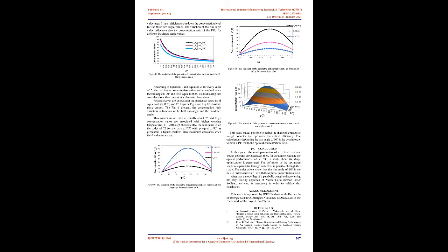Thermal losses from the receiver pipe to the ambient. The net thermal output can be theoretically calculated from the energy balance shown in Fig. 5, and direct solar irradiance, DNI, ambient air temperature, incidence angle, and PTC optical, thermal and geometrical parameters, in addition to the soiling factor, which is calculated as the ratio between average PTC mirror reflectivity during real operation and the nominal reflectivity when the PTC is completely clean. This net thermal output can be given by the following equation.